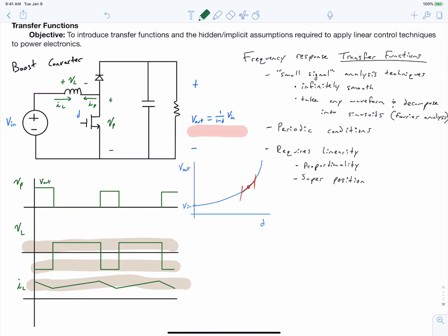So this should be a familiar concept to you from your linear circuits courses. You've previously learned that a technique to solve a circuit that consists of multiple voltage sources is to use superposition, where you solve the circuit once for each voltage source, where that voltage source is turned on but the other voltage sources are turned off, and then you sum up the resulting currents in order to get the final circuit solution. So that was using superposition, and we'll be able to use that same technique in the types of systems that we're describing.